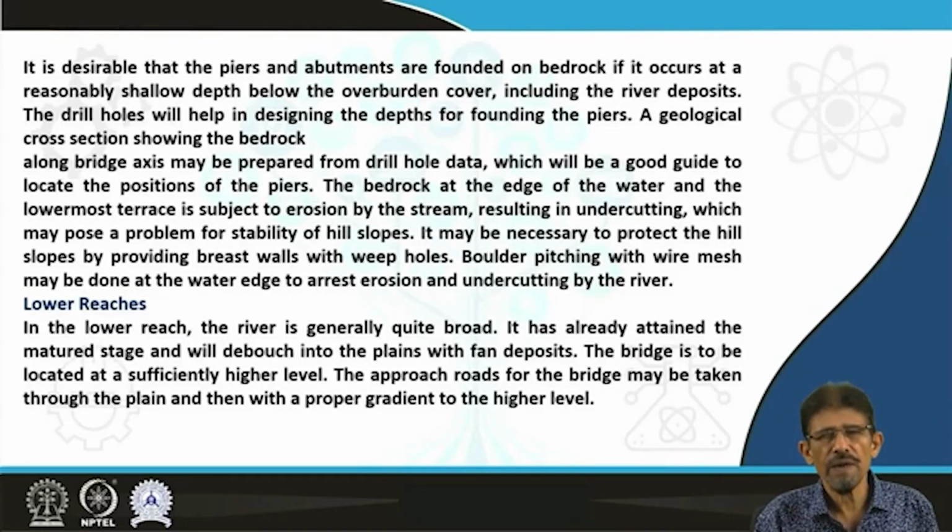In case of middle reach, the river is in an advanced stage and forms a well-defined channel of considerable width, and requires a multi-span bridge with a number of piers besides abutments. It requires detailed subsurface engineering geological investigations through mapping, through geological section preparation, through exploratory drilling, etc., along with geomechanical property evaluation of rocks as well as the rock mass lying below.